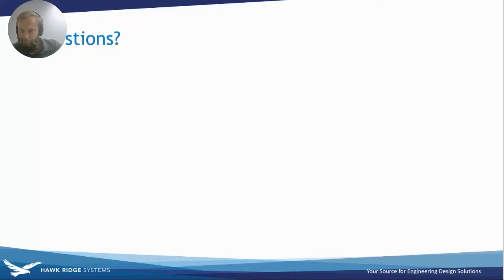Yeah, so a question just came up. Basic simulation comes with any SolidWorks package, I guess. So any CAD level, so standard, professional, or premium CAD does come with Simulation Express, which is a kind of dumbed down version of doing a linear static analysis. But if you wanted to do more functionality, like mesh controls and the hotspot diagnostics, like what you saw from Dane's presentation, that does require a simulation add-in starting with Sim Standard. So there are different levels to simulation as well that give you that functionality.